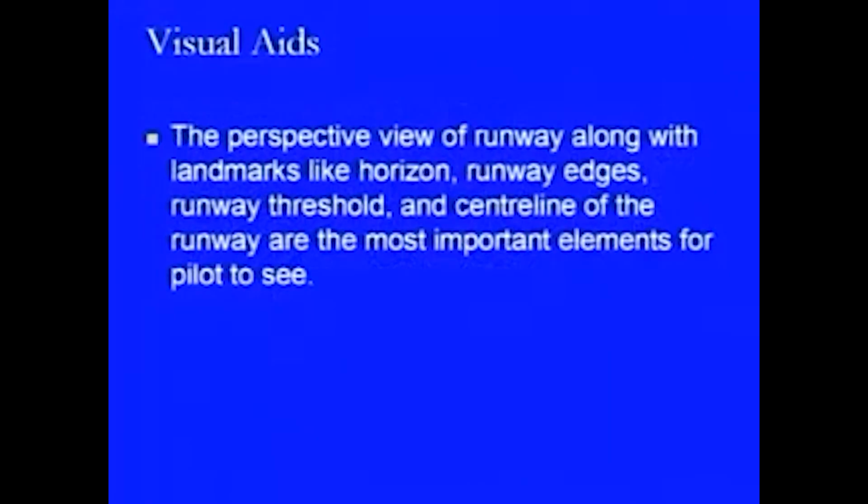The perspective view of the runways along with the landmarks like horizon, runway edges, runway thresholds and center line of the runway are the most important elements for the pilot to see, because if any pilot is making a landing operation, then it becomes very important for the pilot to locate where is the horizon, where the runway edges are, where is the runway threshold which needs to be crossed at a certain height with the specified speed, and then where is the center line of the runway along which the aircraft needs to be aligned, so that the safety is ensured while it is landing.